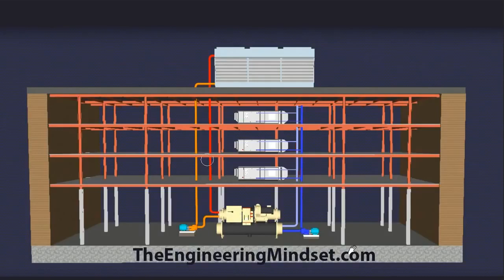That is then pumped up. They're two separate systems, by the way. You should know this from the other videos I've done. But that heat is then sent up to the cooling towers where it's rejected, and the condensed water drops a few degrees Celsius or Fahrenheit, and then returns back into the condenser, ready to pick up more heat from the building.